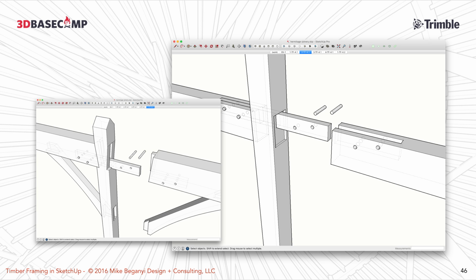So I'll show you what the SketchUp model and the Layout file look like. So here's the Layout file, which has a ton of information on all the post reactions, so that the guy who designed the floor deck, which I didn't do, could get blocking in the right place or posts up underneath the first floor deck. Second floor post plan, and then each one of these things is detailed. Each primary section through the building where there's wood touching wood gets detailed.